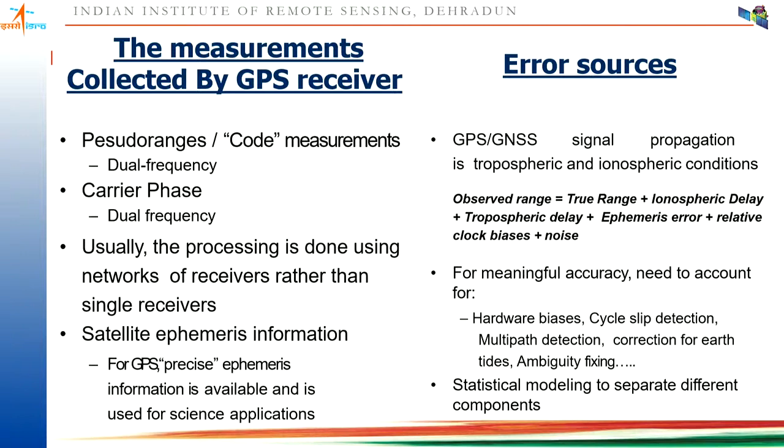On one side, we know the measurements we are receiving at our receiver. What we receive at the receiver is, first, the pseudo range, which is directly the range information, from the time delay between the signal being transmitted and received. The second is the GPS satellite information, that is, the orbital information of the GPS satellite when it is transmitting, which will come into that.